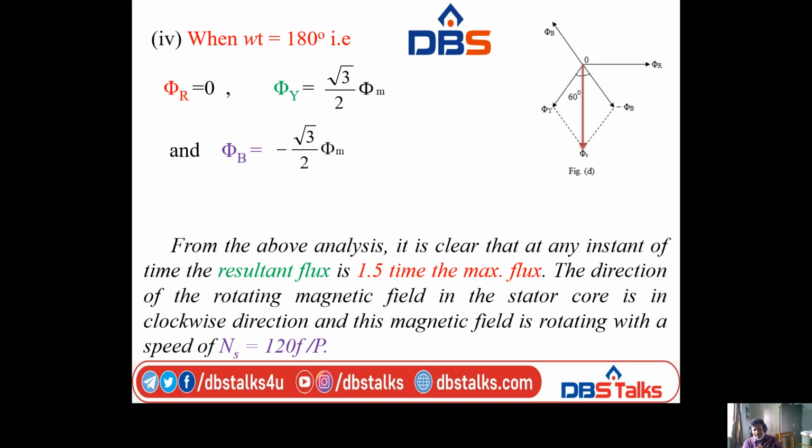So at any instant, whether 0 degrees, 60 degrees, 90 degrees, 120 degrees, 180 degrees, whatever it may be, it is clear that at any instant of time the resultant flux is the same, that is nothing but 1.5 times the maximum flux. The direction of the RMF in the stator core is clockwise, and this magnetic field is rotating with a speed of Ns equal to 120 f by P.